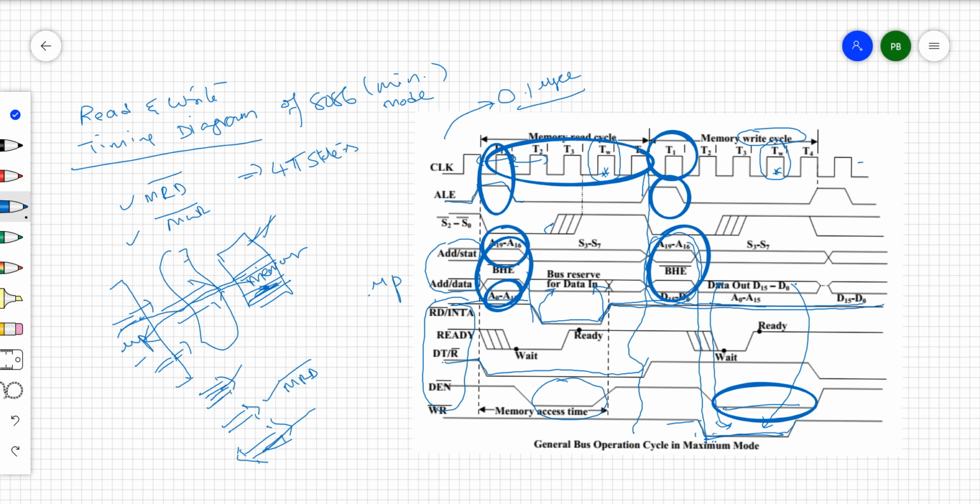Once again, if write is completed, it is high again. Once the write is done, it is also high. So by this time, this second cycle, the write cycle, is also going to be completed. The next cycle may be anything. Based on that, once again these control signals are going to vary. Once again, ALE is high. These act like an address bus, right? Then like that, based on these control signals, the data writing or reading operation will take place, right?